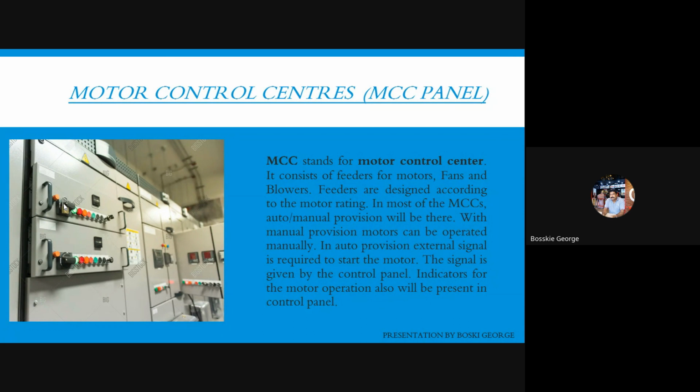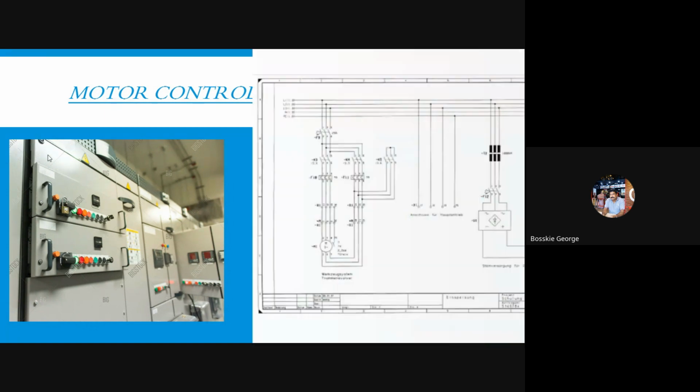Centrifugal fans means big fans with fan blades more than 1000 mm in length; for those we go for soft starters. As the application varies, we design the motor starters accordingly.